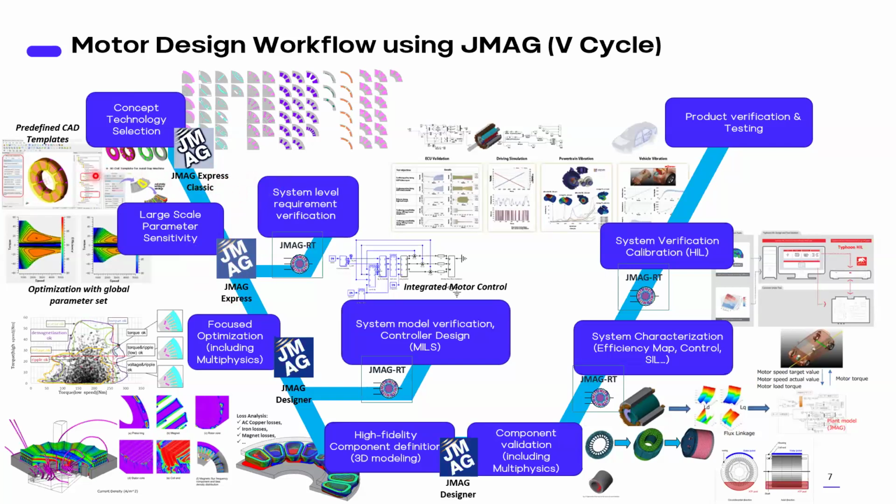Once you give the input, you directly get the output in just one minute, with just one click of the simulation. We also have predefined templates for stator, rotor, everything. We can just select it and the motor will be built. After entering all the details, in a single click, we get the basic torque-speed characteristics, current, and all the outputs can be viewed.